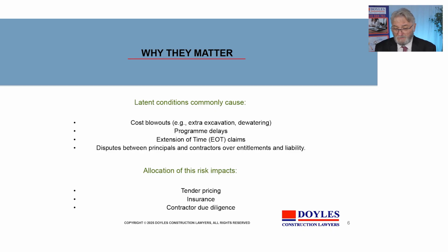And as a result, a large claim developed. The other aspect that happens with latent conditions is program delays, because even if you were lucky enough to avoid a massive cost overrun, it's highly likely that you'll have delays as subcontractors scheduled to do work can't be allowed access, and new contractors to deal with the latent condition claim come into being.